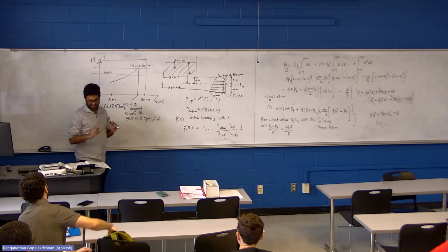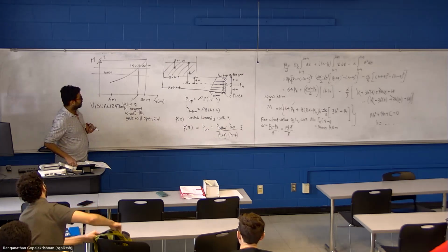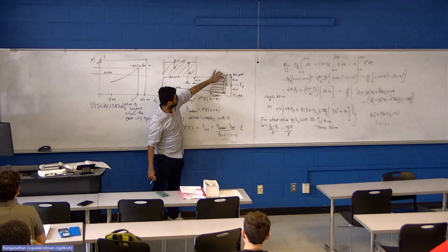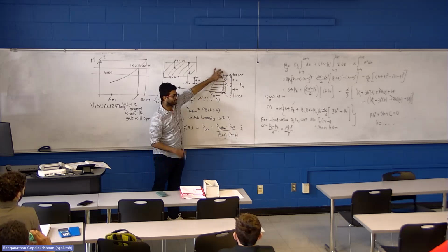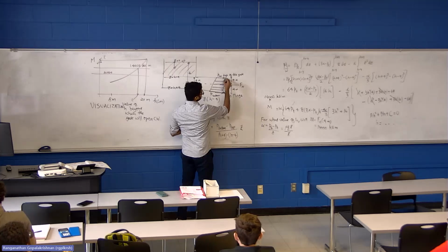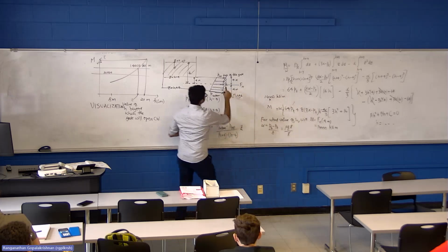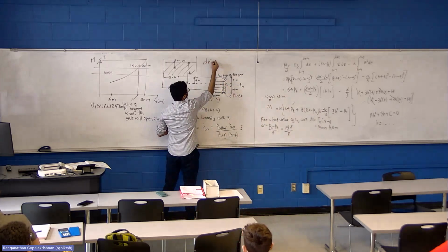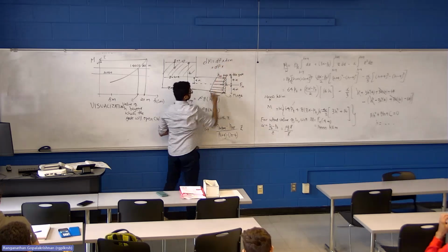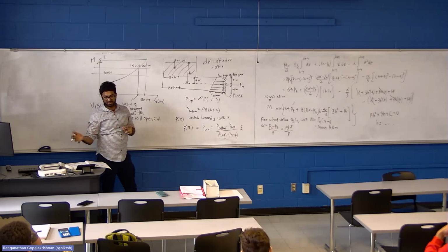The answer won't be, okay, that's a yes or no question the way Dr. Hochstein has worded it. But if you were to solve the same problem, let's say in the exam, I redraw the diagram and make the hinge at the top and ask you to solve the same problem again. You are now trying to evaluate the moment. The only place where this will change is the moment. The moment was dM equal to dF times arm. And what is the arm now if the hinge were at the top? We previously had 8 minus z.